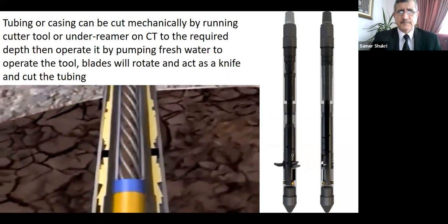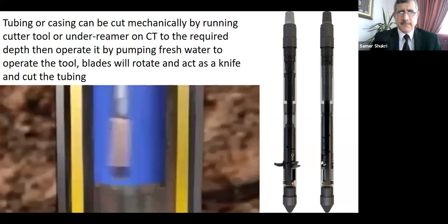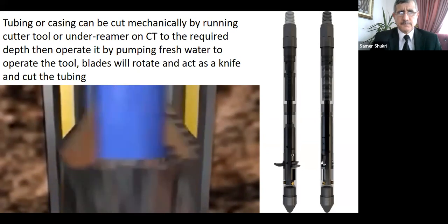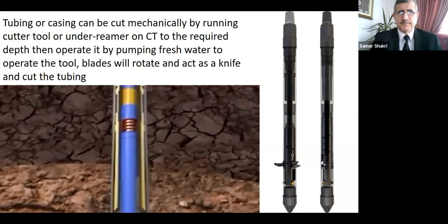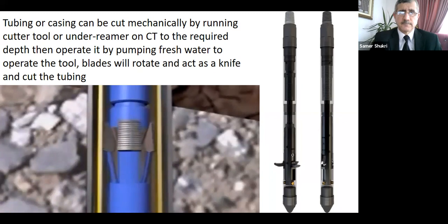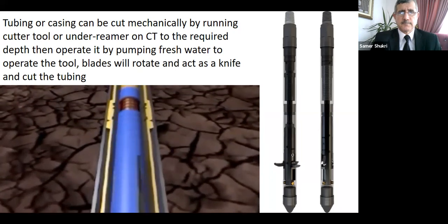You see, here the hydraulic anchor is being used in combination with a DB underreamer with cutting knives to cut the tubing end of a completion. The tubing can be safely cut without the knives of the cutting tool moving over the tubing wall. Tubing is cut now using the knives. Pull out of hole. When the tubing is cut, the anchor will release by simply pulling out of hole. Interesting.